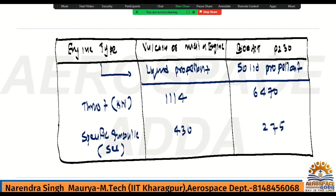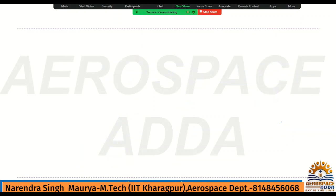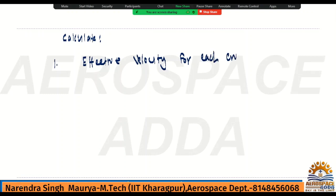See that, for liquid propellant I had given the advantage and disadvantage. That time I told you that for a liquid propellant engine ISP is more. Check the ISP: 430, and for solid we have 275. Now this is the table. For this table, what do we need to calculate? We need to write: calculate number 1. What is number 1? Listen carefully. Effective velocity for each engine.